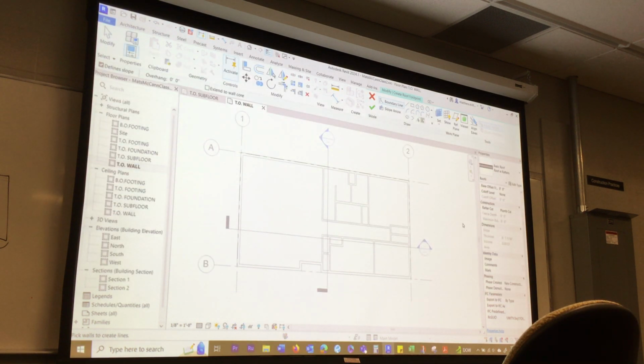Can we draw the roof yet? No, gotta do a few other things. Alright. So we're gonna work with boundary line, gotta have that set, so it should be there by default. Where's our base offset gonna come from? I think probably right there. And cutoff level, none, do I want a plumb cut? No, we're just gonna leave this at 0 and see where it ends up.